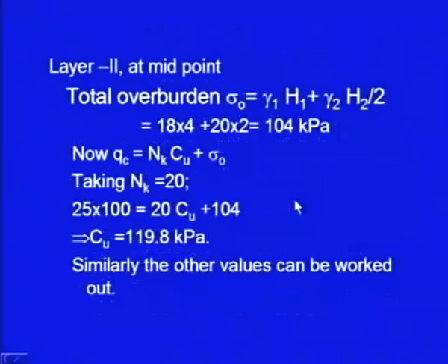So, friends, we have discussed the penetration tests. The first penetration test was the standard penetration test, in which a borehole was required. The second penetration test was DCPT, the dynamic cone penetration test. This was a very quick, very cheap test, but it is used only for supplementing the SPT results. And the third test we have discussed is the SCPT. All these three tests are very important, and we have discussed them in much detail.